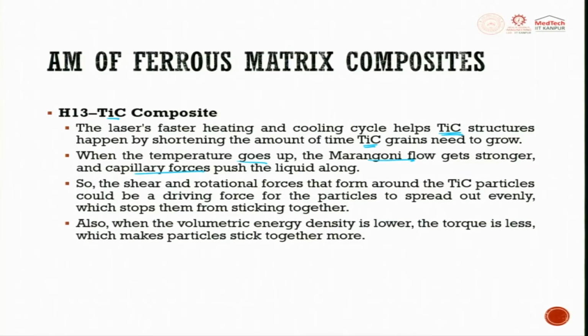Movement can happen, Marangoni flow. The capillary force pushes the liquid along. So, now there have to be both, and these two will try to disperse TiC and give you a well dispersed H13 metal matrix composite. The rotation is through Marangoni, capillary is here. So, the shear and rotational force that form around the TiC particles could be a driving force for the particles to spread out evenly, which stops them from sticking together.